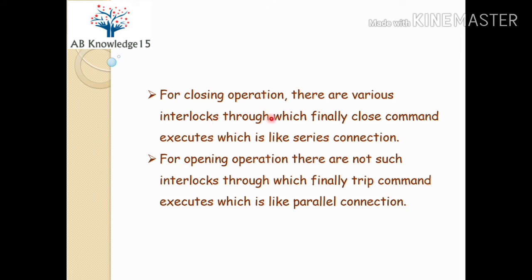So these 3 to 4 interlocks come into picture while closing command, and due to this it is creating like series connection of command. So that's why the closing operation takes some more time than the opening operation.